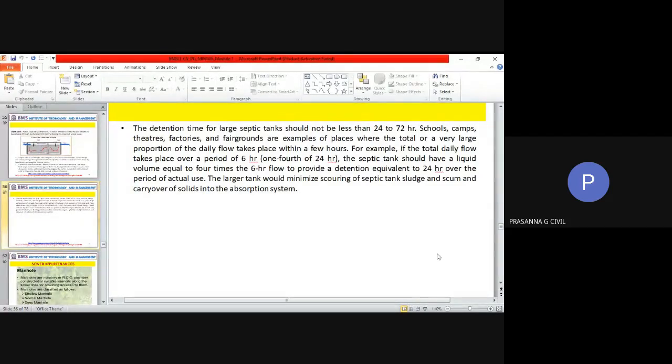If they have agricultural land, it can be sent to the subsoil there so that it moistens the root area. But by that time, it would have been cleared off from all the solid matter that is present in the wastewater which comes to the septic tank initially. So whenever you think of septic tank, think as a soak pit attached to it. Both systems work together. So this is about the low cost treatment unit, which is being included in your first module because this does not get covered in any other space.